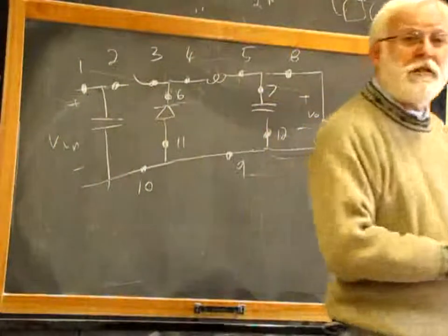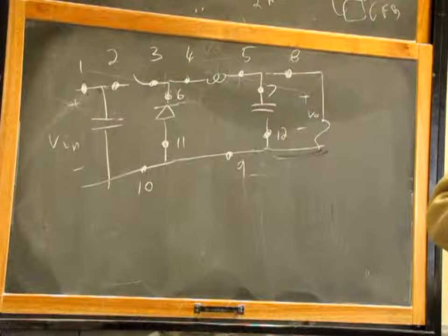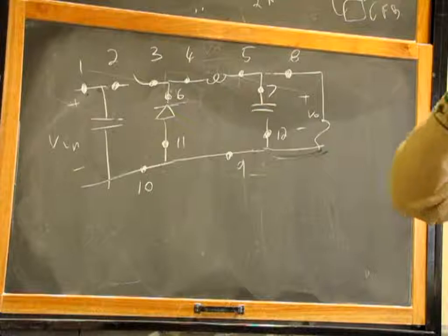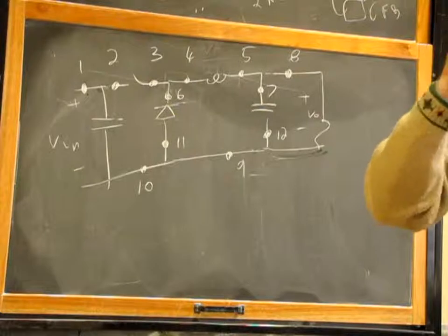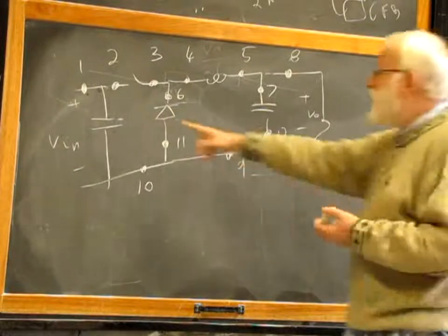Remember, what do I want to measure? The peak current of the inductor. Because that is when the inductor current reaches the peak, I want to open. The peak that I set for this working condition, I want to open the switch. Is this okay?